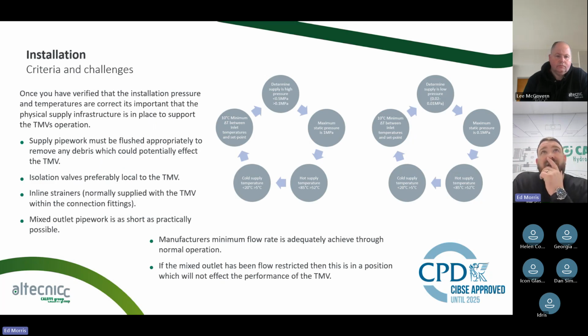Installation wise, so criteria and challenges. Once you've verified that the installation pressures and temperatures are correct, it's important that the physical supply infrastructure is in place to support the TMV's operation. This is really key. From my perspective as a technical manager, and my team's, a majority of calls that we deal with about issues with thermostatic mixing valves come down to the system itself. It's the way that the system actually performs.